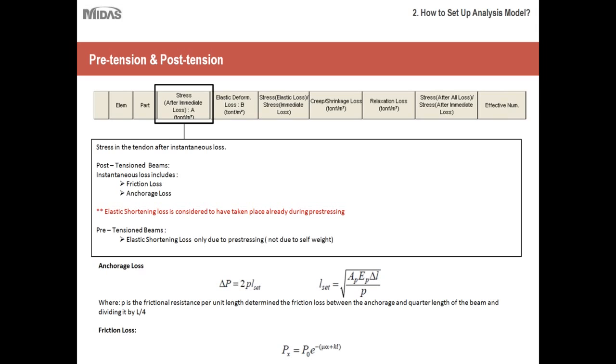Depending upon the type of tensioning you are applying, whether it is pre-tension or post-tension, there will be different types of losses. So it is sometimes really hard for any software program or for engineers to consider these losses separately. What they do is either they just lose track that it was a pre-tension tendon strand, and they apply and compute the post-tension tendon losses. So there's a lot of scope for human error that keeps all the engineers on their heels.